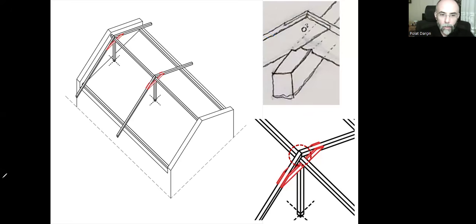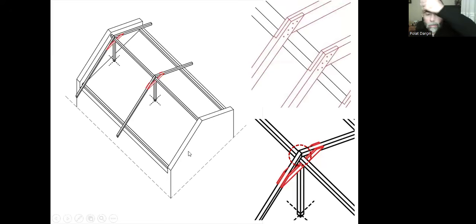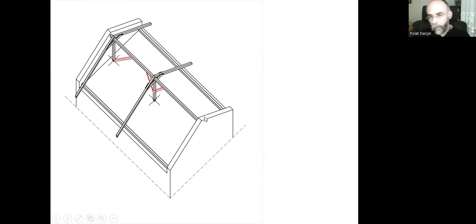in their center. Here, there is another perspective that we can understand the system in a better way. Instead of creating one single hole and using a big bolt, we can nail them together from many points. And we will be supporting the connection between the purlin and the stud using these bracings. Only one bracing if it's on the wall side, two bracings in the middle stud.